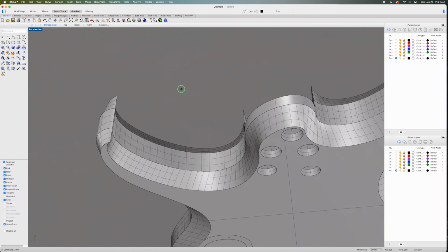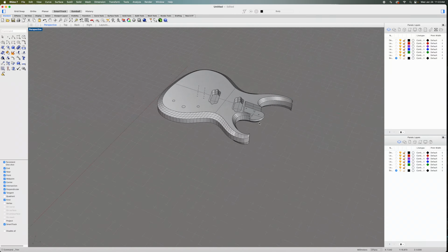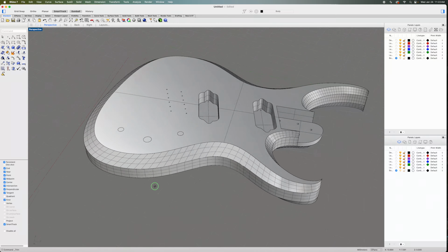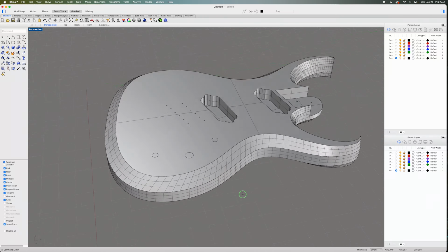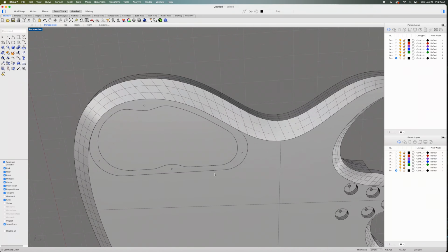So now we have the holes for mounting the neck. Okay. Now we're going to do the control cavity. And there's several elements here. There's this outer line, which represents the recess for the shelf that the cover will sit on, because I like my covers to be recessed into the body. And then this shape is a natural indication of the shape of the pocket itself.